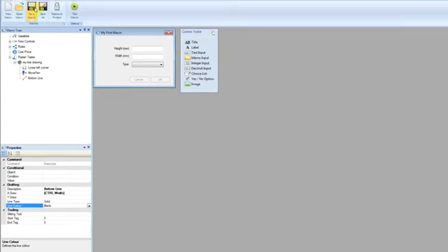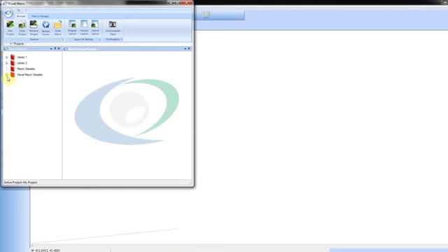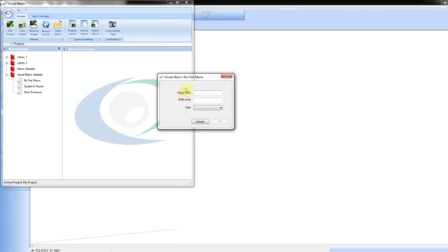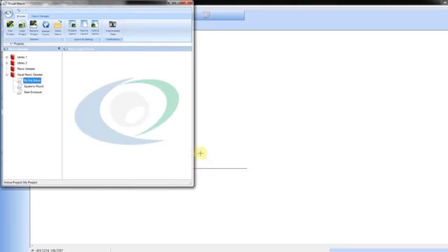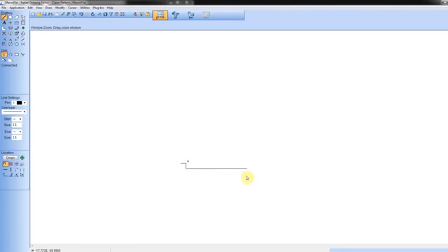For our example we will leave these properties at their defaults. OK. Save the macro and close the workbench, and if there is a Radan drawing open, start a new drawing. Open your macro and enter some valid answers and click OK. Your Radan drawing should look something like this. OK. Close the drawing and return to the macro in the workbench environment.